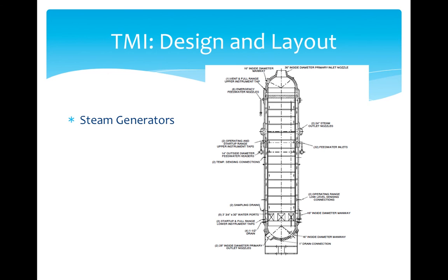With the pressurizer, the plant also had two steam generators that were designed by Babcock and Wilcox. These steam generators were once-through type that were 92 feet long with the bottom below the core inlets. They were designed this way in order for the primary side to develop natural circulation in the event that the coolant pumps were not running, or if there was only a limited amount of cooling water on the secondary side. The purpose of the steam generator was to remove the heat that was on the primary side and use it to create steam on the secondary, thus resulting in driving the turbines that were used to create electrical power.